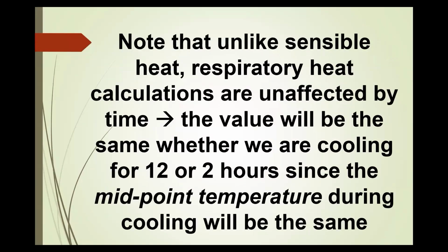Note that, unlike sensible heat, respiratory heat calculations are unaffected by time. The value will be the same whether we are cooling for 12 or 2 hours, since the midpoint temperature during cooling will remain the same.